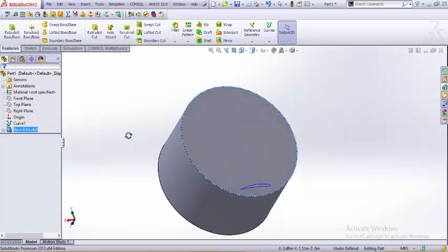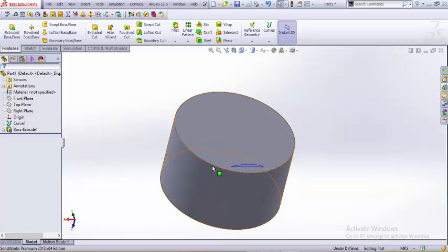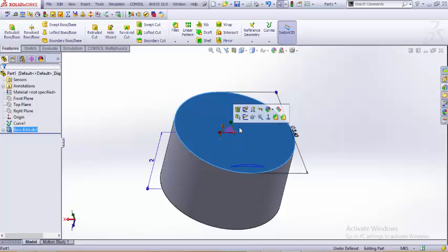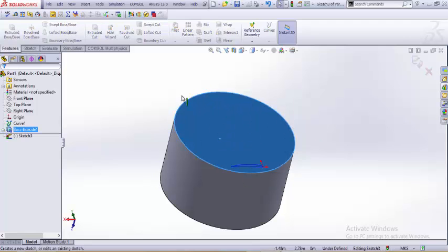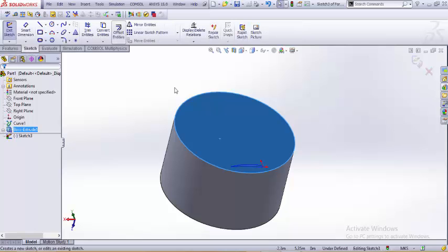Another thing to be noted, the more you can utilize this cross section, the more we get a positive lift, and for that we might just go for a helical blade. For that we use this edge as sketch and sketch on this plane, convert the entities.